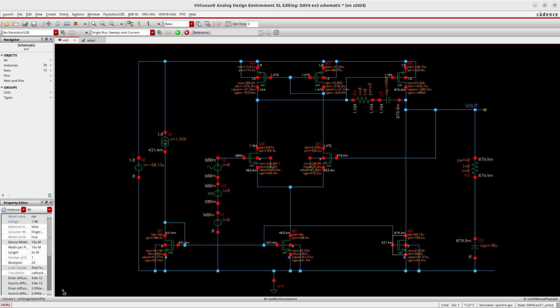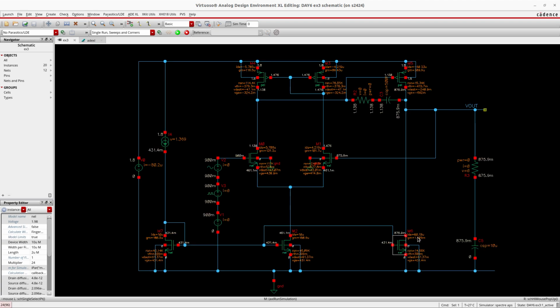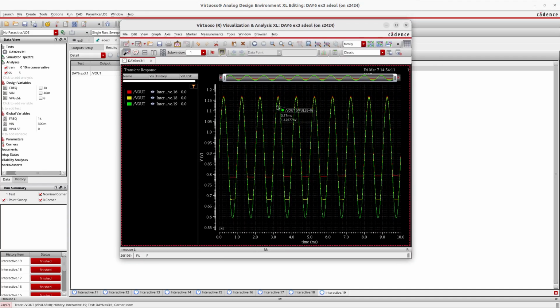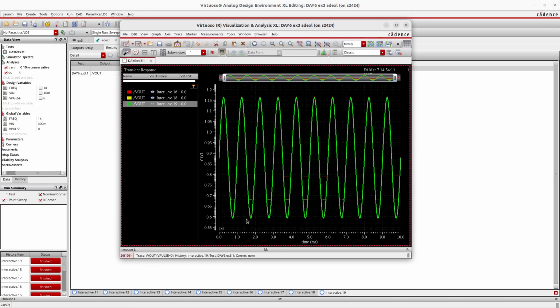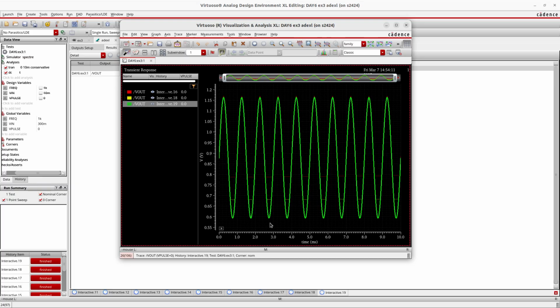We put 24, and then that will give us 60 microamps, which is the absolute minimum that we need to be able to drive that resistance. And then we get the 60 microamps, and we take a look at the output. And now we have the full signal swing at the output. Okay, we have the full signal swing at the output. Now the buffering is linear.